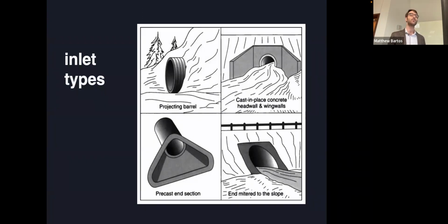Why do you think we might want an inlet that contracts and has a smooth transition in width? Do you have an idea? So the slow velocity. It might be. So we'll get back to this later. There's a specific reason, and think perhaps to something we looked at earlier in class. It would decrease head loss, yeah, if you have a smoother transition. I'll give you the answer a little bit later on when we get to what are called inlet control culverts. But just think about that.